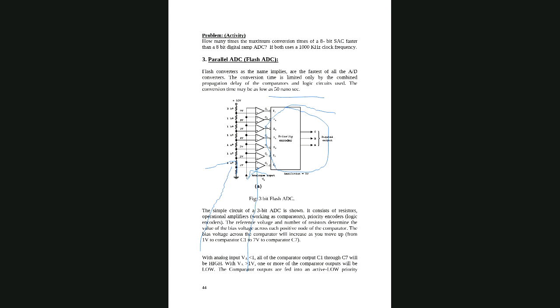Comparator, everybody knows well. We have seen the comparator before also. We have a negative and a positive input. It's very simple. If the positive is more than the negative, the output will be 1. If the negative is more than the positive, it will be 0.